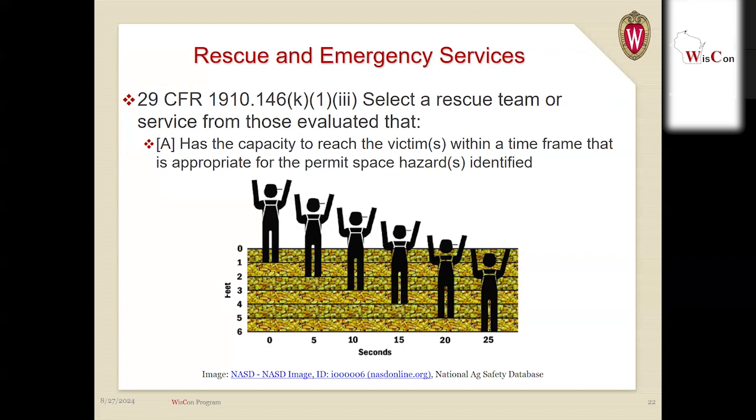And you also have to take into consideration that even if there's a response time that is 2 minutes, it's going to take the team time to get things set up, right? Because the team doesn't just jump into that confined space. They usually also have to put on gear. They have to put on retrieval lines. So it's not just arrival time, it's arrival and setup time. So there can be a delay in actually performing the rescue. So you're going to want to keep that in mind.